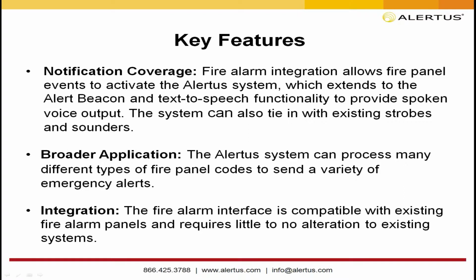So the last piece of integration that I actually skipped was that we are actually able to leverage the fire panel speakers that are already in throughout your facility. That's something that the code at NFPA actually allows us to do. It allows us to be able to leverage those speakers to use for mass notifications.